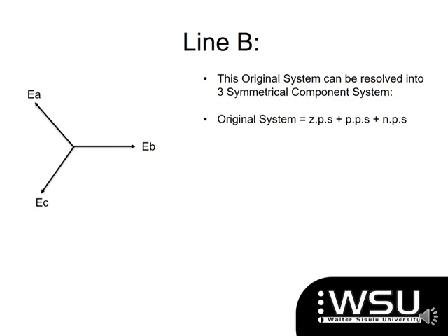What you simply did is you took that B or that C phase and you rewrote it and you said it was just A phase. You ignored the fact that it was not A phase and you made it by force A phase, which also now affected the other things that you had to calculate, because your impedances were also in A, B, and C phase, and your voltages were also in A, B, and C phase. So therefore, when you had to go and work out, you now were unable to, because everything was not matching accordingly. So this is how you needed to go about doing it.